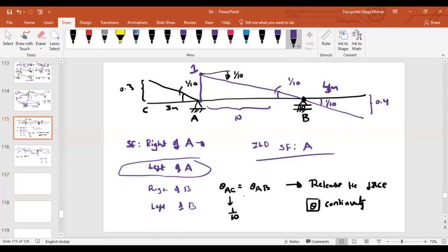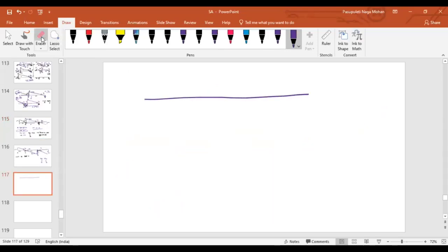Diagrams are clear, right? The two diagrams, how they have drawn. Yes, sir. This two diagram is clear. Right of A and the C. Yeah, right of A and left of B, that's fine. Now try it for left of A and let me see. Make sure that you should not forget the continuity requirement. If you're drawing for shear force, try to see the continuity requirement of slope. Always try to see the requirement of slope. That is where most of the diagrams will lead us to correct answers. Meanwhile, if you guys are having any doubts, let me know. I will clarify your doubts.